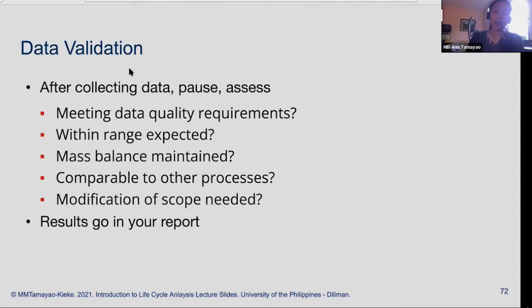Again, emphasis on data validation. After you collect the data, you should take a pause and assess. Is the data meeting the data quality requirements that you have stated from the outset? Are the data that you have within the range that are expected? Are the mass balances maintained? Is it comparable to other processes? Is there a modification of the scope that is needed given your data collection experience so far? And of course, the results of this data validation process should go in your report.